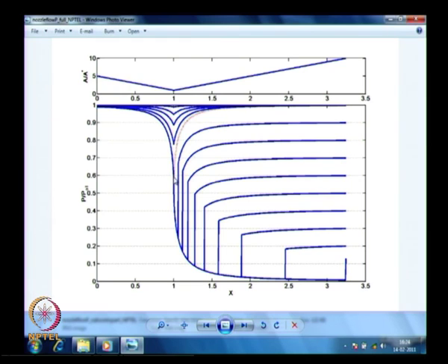After that, I am going to have different curves. If I pick this PB by P naught 1 as 0.9, then it goes through this up to here. The shock is sitting at this location, and from there it is jumping to some other pressure and going through the remaining part as a subsonic solution. And you can see as I decrease my back pressure, the shock is going more and more downstream.